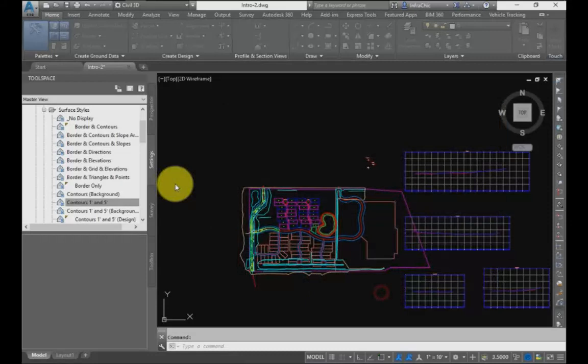As you can see, there are many settings available on the Settings tab. You can configure all of this information to your exact needs within Civil 3D. And to simplify things, once you have the settings configured properly, you can save them in a drawing template. Then you can use the drawing template to begin your new drawings with all your preferred settings already configured.